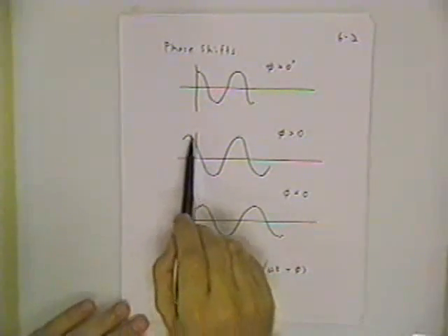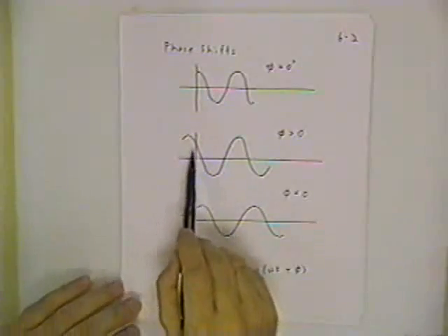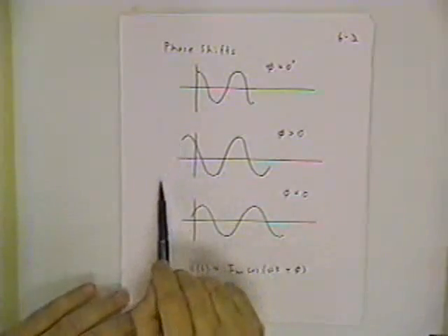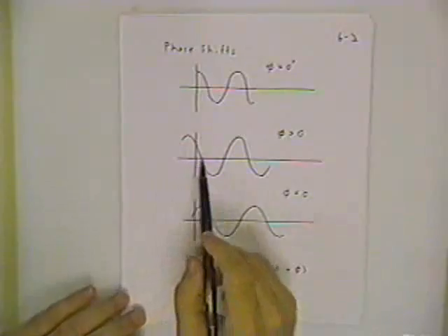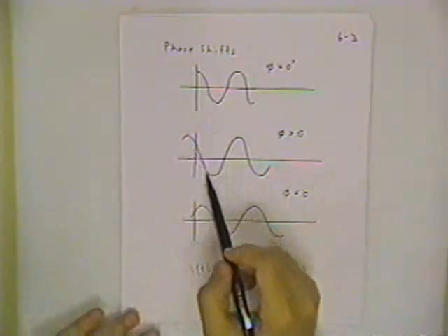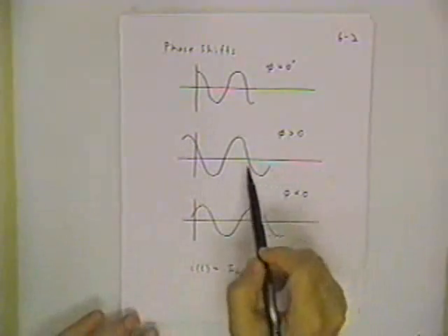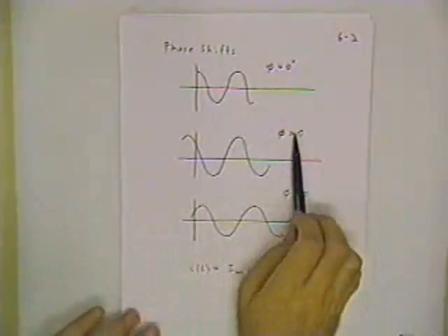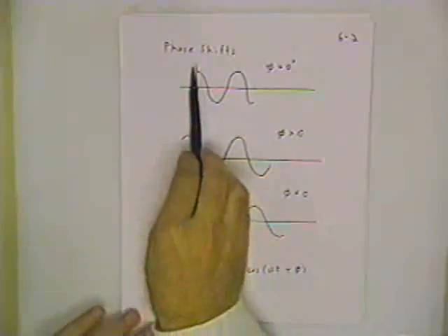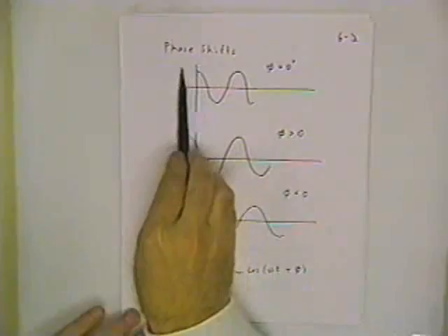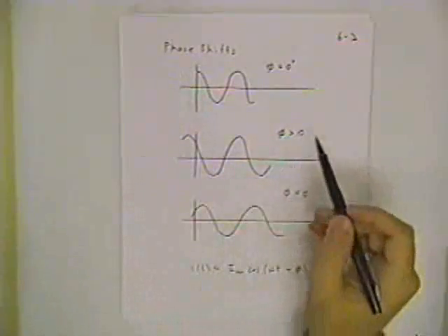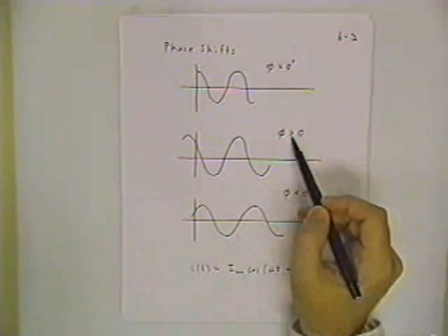Now, you could also think of that as the axis staying fixed and the cosine having slid over to the left a little bit. Personally, I prefer thinking of the waveform as the fixed object, and then whether my phase shift is positive or negative takes this time axis and shifts it over to the right or to the left. I think it's intuitive from the number line.